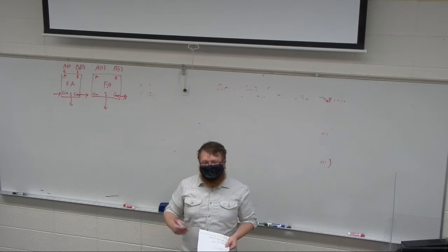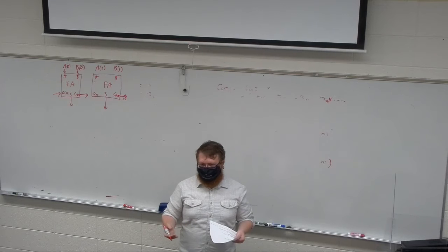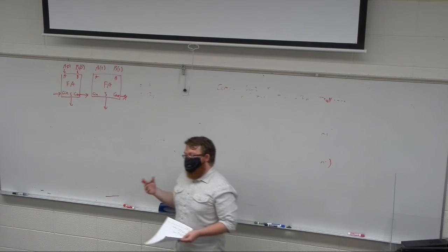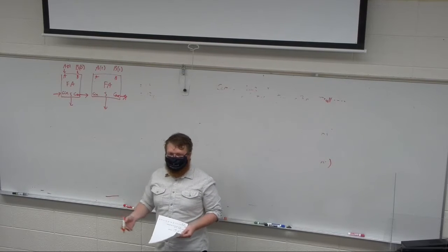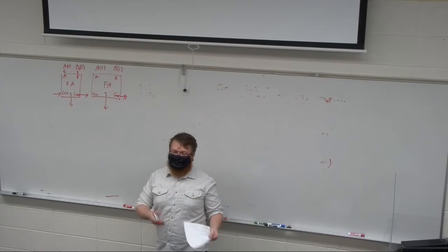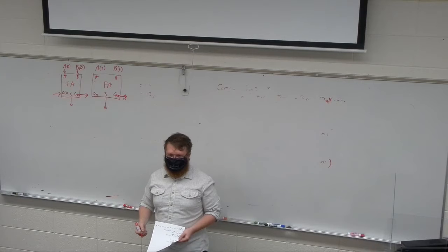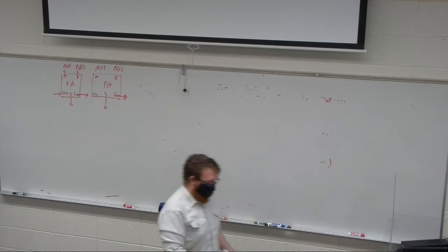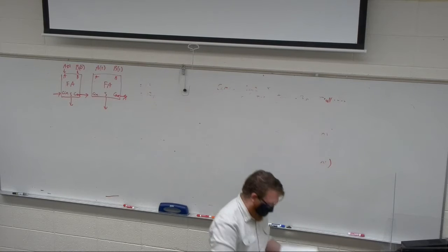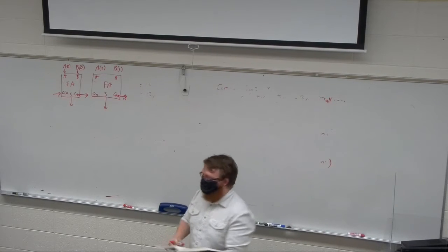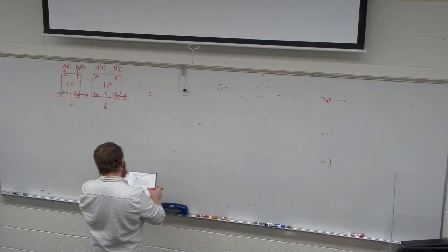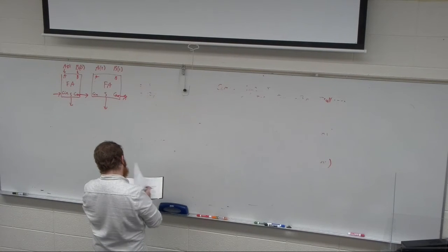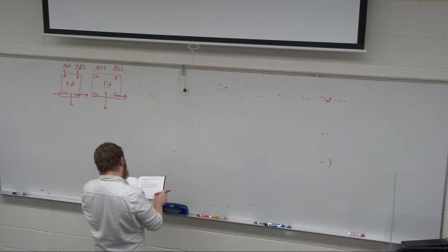Well, there's a nice little technology that a couple of students have stumbled across called generate. What generate does, incredibly helpful, is it generates, using a loop, instances of the component for us. So let's build up a nice, simple example of those. I'll start with the generate statement, I think, might be the easiest.